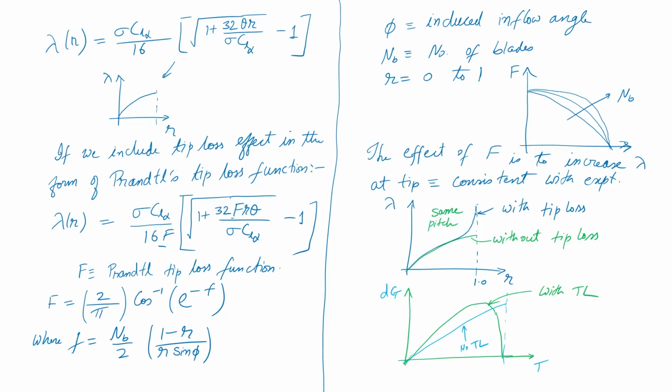And beyond that, at the end you will also get to implement this tip loss factor and see how it actually changes your lift distribution. So, you will actually plot this dCt versus r and see it for yourself. Okay. So, let us quickly look at the approach to implement this tip loss function in BEMT.